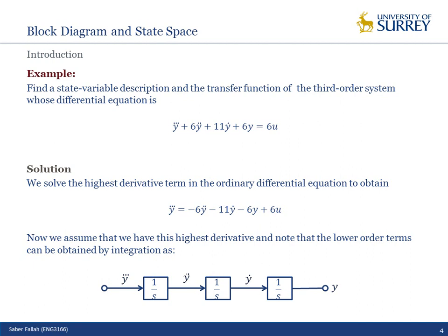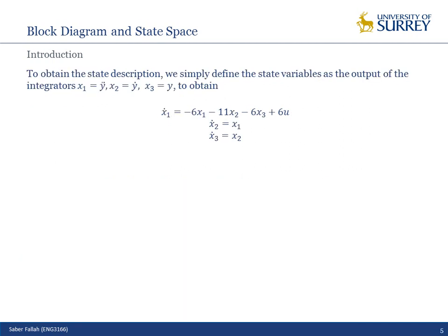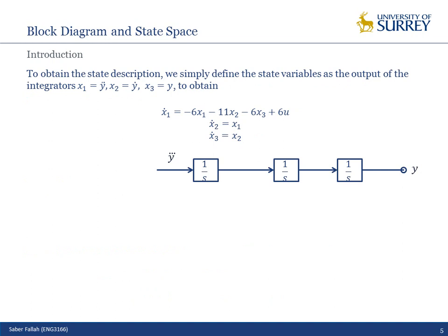Okay, so how can we represent this one, the state space, in the Laplace domain? Again, look at the block diagram we have. The highest order is y triple dot, and I need 3 integrators to get to y.